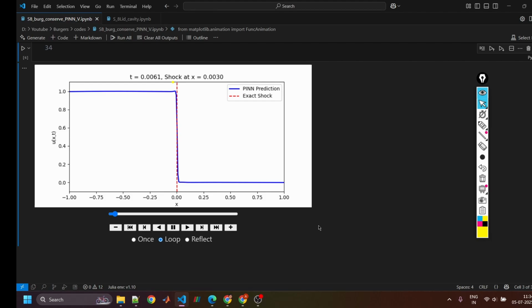The only difference is that when we go for problems having shocks, it's good to use the adaptive viscosity PINN. In the next tutorial, we will solve the Euler equation. When we solve the Euler equation, sometimes it's hard to stabilize the solver using adaptive viscosity. In that case, we will see another concept that we call the adaptive weight viscosity PINN. So now I hope you got a little bit of an idea how to solve the Burgers equation. I have provided this code in the comment.